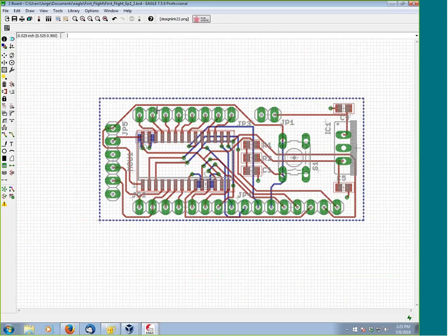If you're going to have the manufacturer assemble the board, in other words, you're going to have them solder the components instead of you doing it at home, 9 times out of 10 they are going to ask you for a pick-and-place file. It goes by various names. You might see XYRS. You may see as well Centroid file. They all represent the same thing. It's basically a file that contains all of the component locations as well as their rotations on the board and what side they're on.